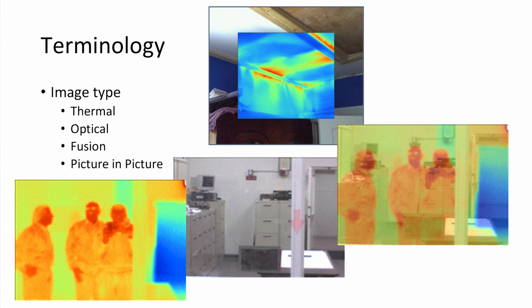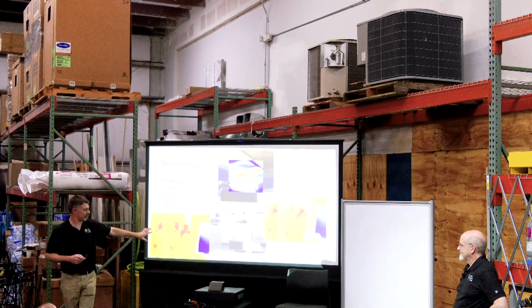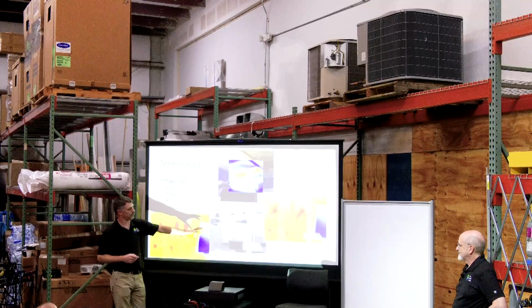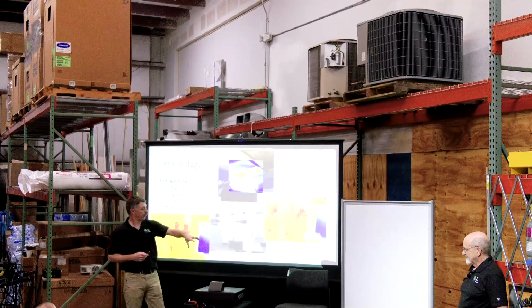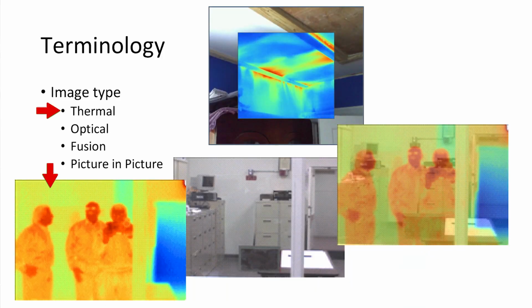wall. So when that image was taken, these people, which appear to be standing there, are not really standing there. Their heat is being reflected in that glass wall. So it looks like they're standing in the room. And this is one reason why visible images are so important to correlate to thermal images, because like Bill pointed out earlier, if you look at this image alone, why the heck are there people standing there? Well, there weren't, right? But I can't see the heat signatures of all that stuff behind that glass because the glass is in the way and it's showing me what's behind here.